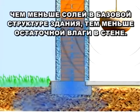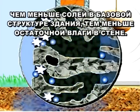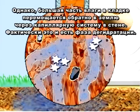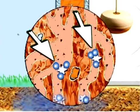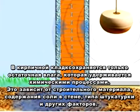The fewer salts there are in the basic structure of the building, the less residual moisture remains in the wall. However, the large part of the masonry moisture moves back into the ground through the capillary system in the wall, which is the actual phase of dehumidification. What remains is the chemically bound residual moisture in masonry.